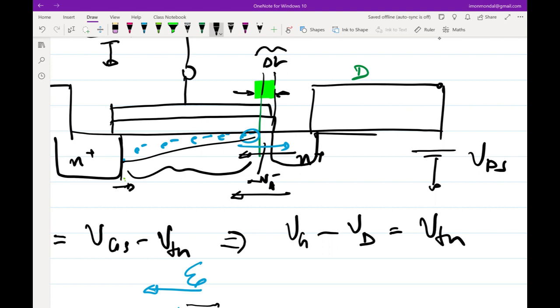And what is that voltage that is remaining across the channel? It's equal to that voltage which appeared during pinch off, almost equal to that voltage. There will be some additional drop, but with respect to the original voltage, I can argue that the voltage across the channel remains exactly equal to VGS minus VTH, because at that value of VDS, we hit pinch off. Make sense?